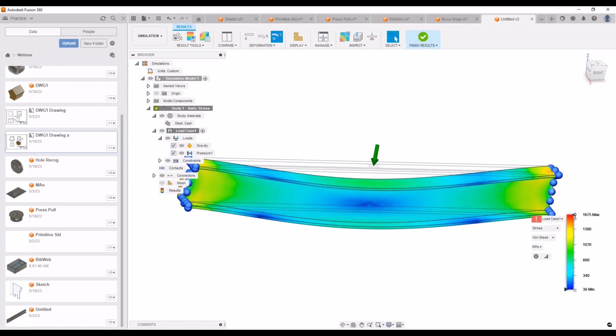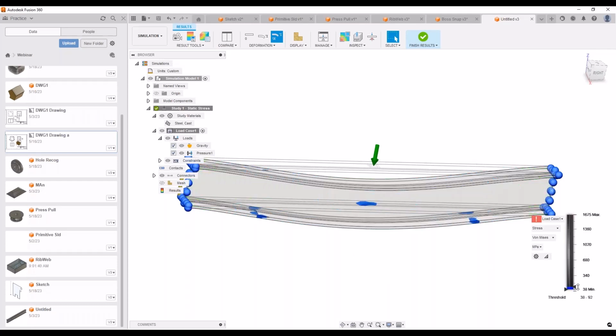Now you look at your minimum section, like over here, you've got very little stress. In this case, I've obviously gone with a very big force, so that will not be worthwhile. But if the force is a little bit less than your maximum force as you've calculated, you'll be able to check which sections you can remove material from without losing too much.